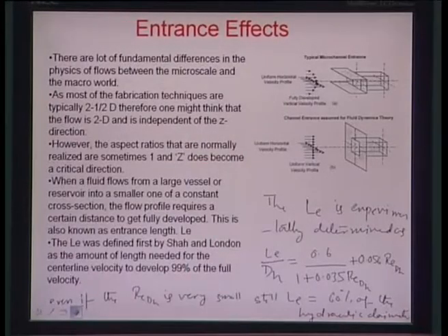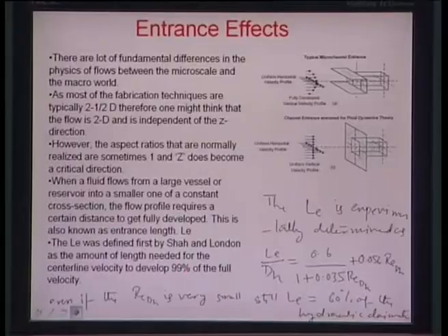So one more interesting paradigm to be evaluated in microfluidics is related to the effects which can come at the entrance of a microchannel. As we know, as a channel is approached by a flow of constant velocity and pressure-driven flow, the moment after the flow enters the channel, there is always some time which the flow takes to get fully developed, where this parabolic profile of the flow gets created within the microchannel.